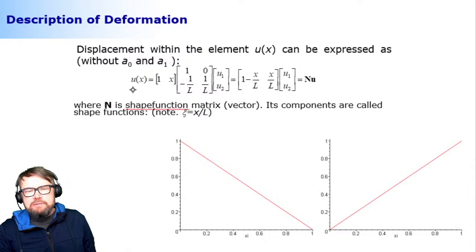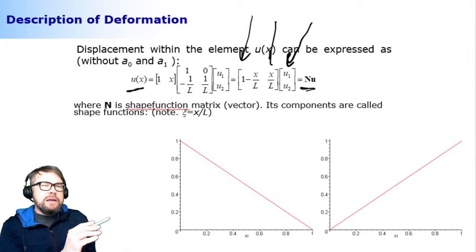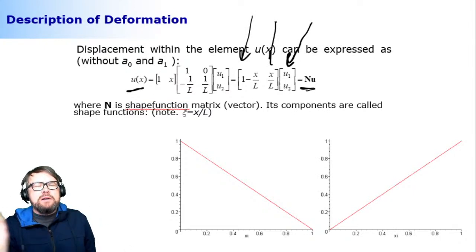So once I compute everything, I have an approximation of the displacement. And the displacement will be expressed by N, which is my shape function matrix, and the vector in this case, because we are looking at the planar case, of nodal degrees of freedom. These are the nodal degrees of freedom. These are the shape functions. They are telling me how particles are moving if one node is moving left and right. That's about it. And this is all about the finite element method.